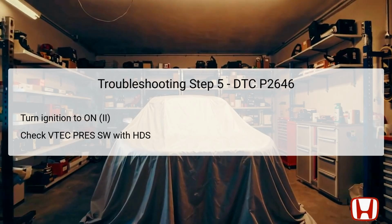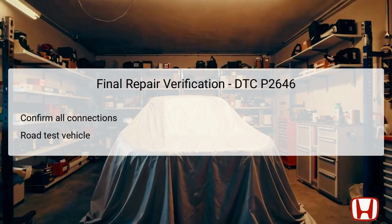After completing the necessary repairs or replacements based on the troubleshooting steps, it's essential to conduct a final verification to ensure the issue has been adequately resolved. Start by confirming that all connections, particularly those related to the rocker arm oil pressure switch and the VTEC system, are secure and free from corrosion or damage.